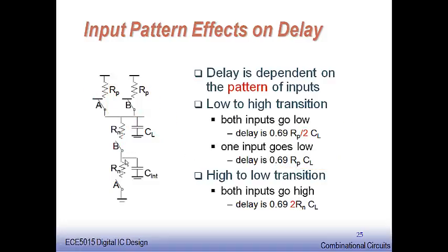What other effect also is to be considered is the CINT capacitance. We had taken the case of a 1 here and a 0 and a 1. Now the charging current flows like this, charging the CL, and we find even this transistor also is on, the B device also is on, which makes the CINT also get charged.